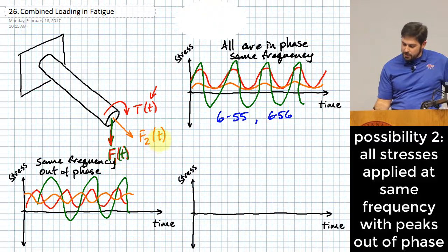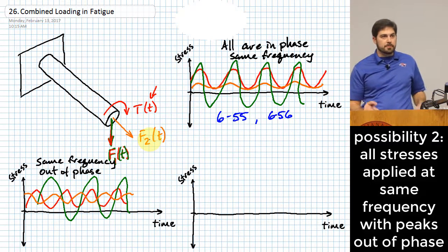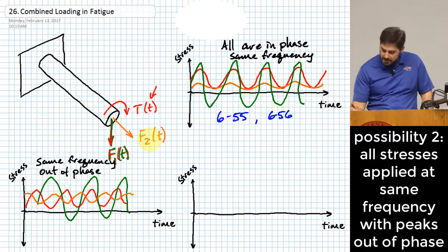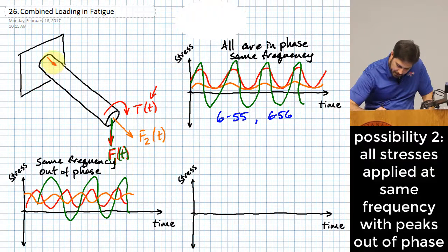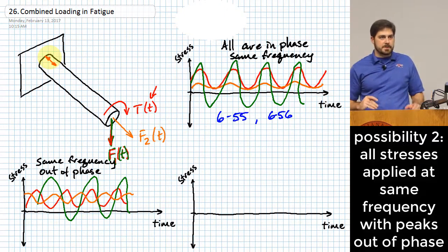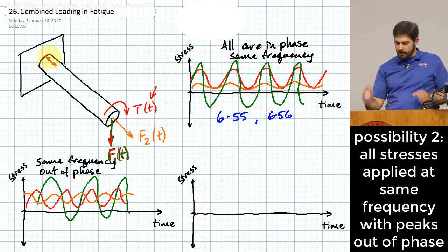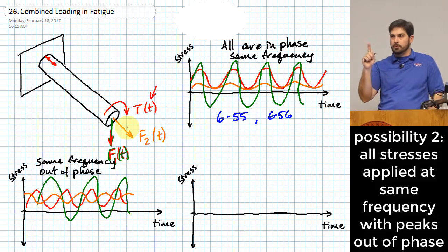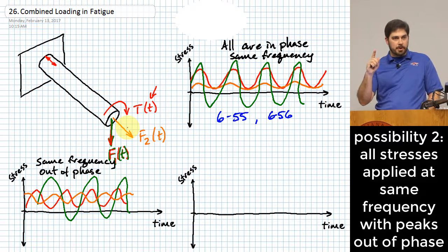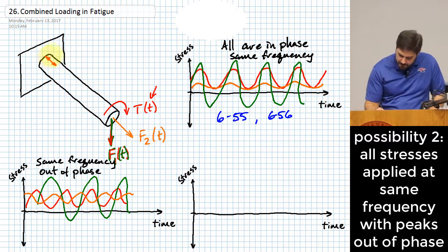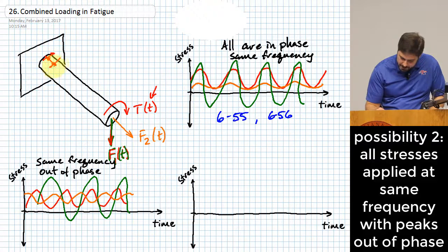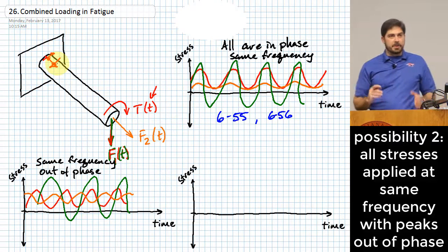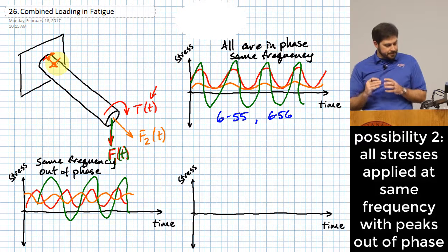Your bending and your axial loads will both create stresses in the axial direction, right? Does that make sense? Both for flexure as well as for axial, those are both creating stresses in the same direction. So you have one component of normal stress that is created from those two, and then you have a component of shearing stress that's created over here, and you combine those together.